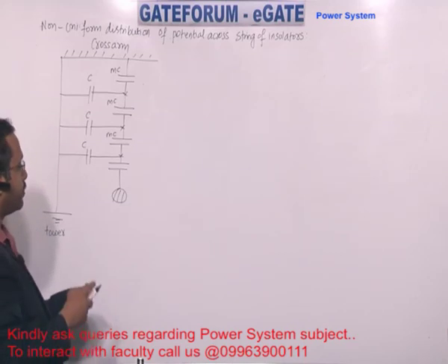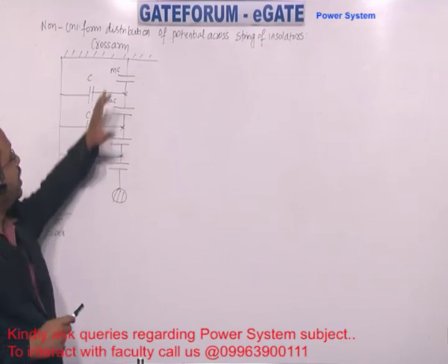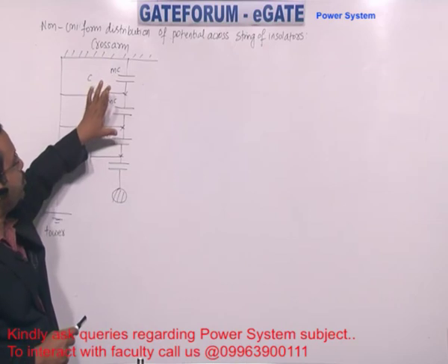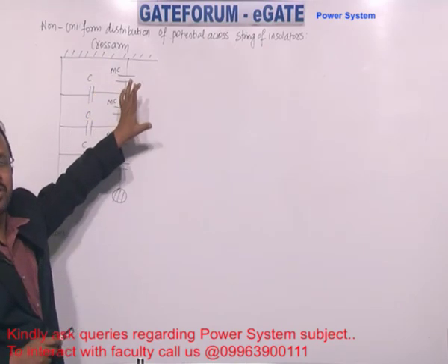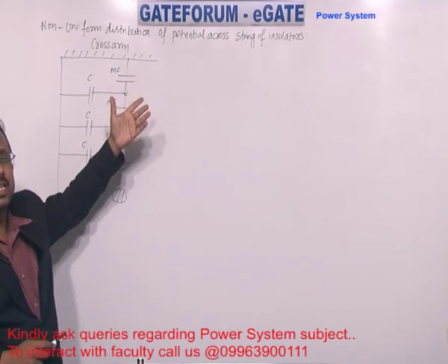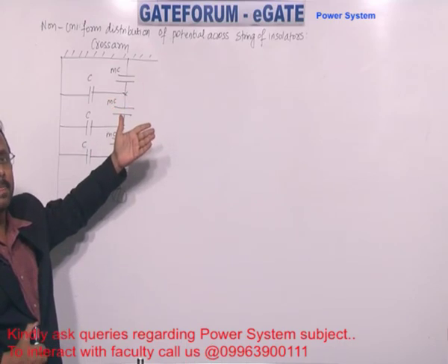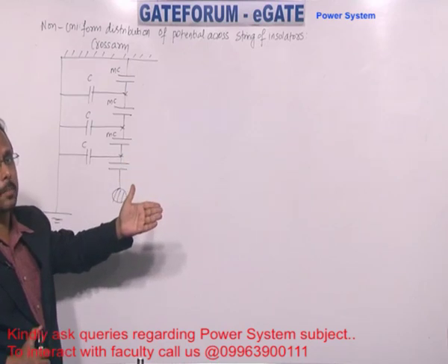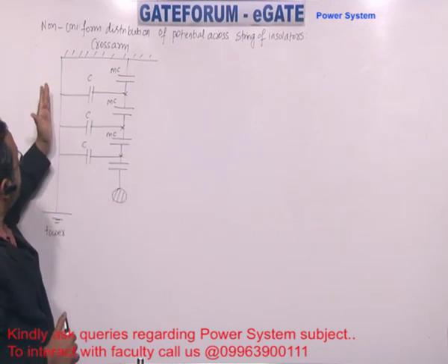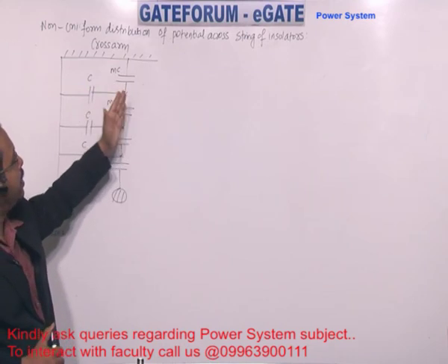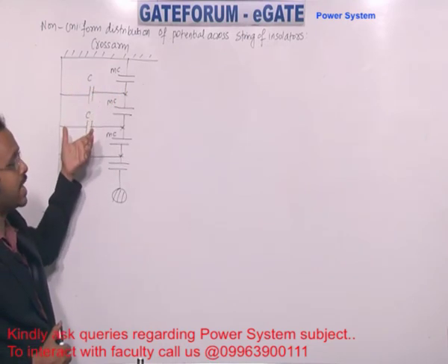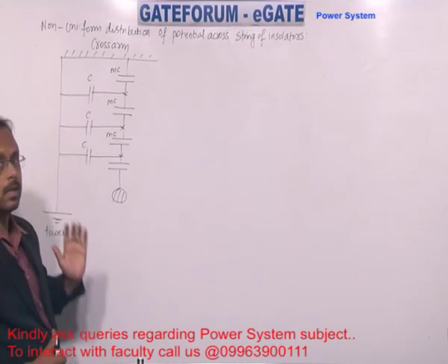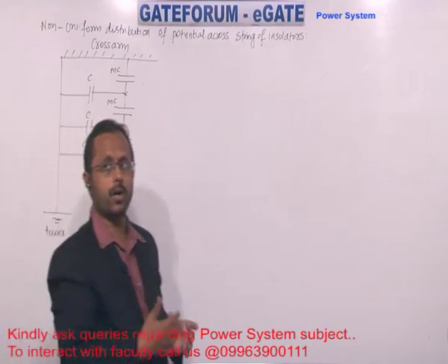So you indicate the tower structure, cross arm, and any two insulators connected by a metal part. Between two metal parts we have dielectric, which is equivalent to a capacitor. So electrically an insulator is represented using a capacitor. Tower made of metal, here a metal part, in between atmospheric air acts as dielectric, so you get another capacitor. Further analysis we continue after the break.